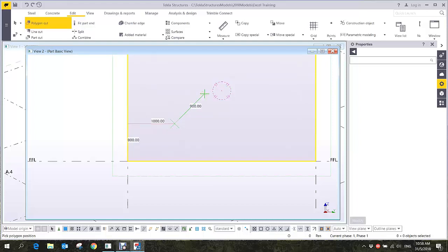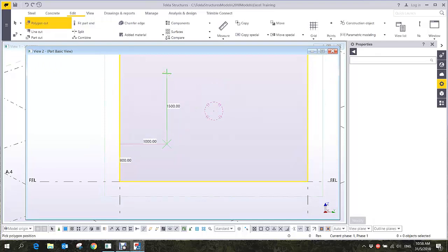So control is something like transferring the origin or the reference to that point. So in this case, I can just simply click here 1650, 2000, 1650, and then much easier, right? But you need to master how to use the control key.